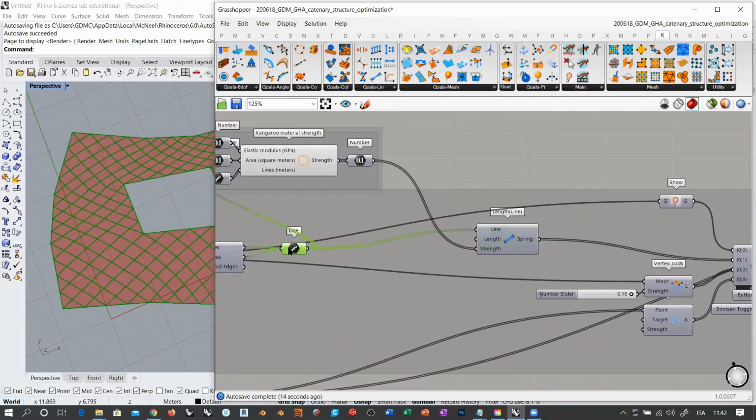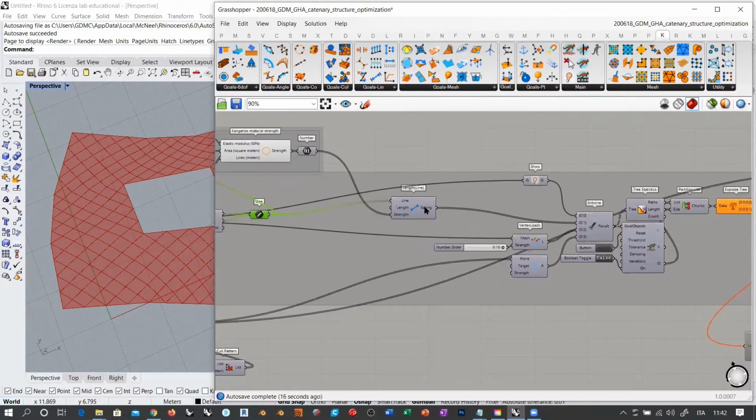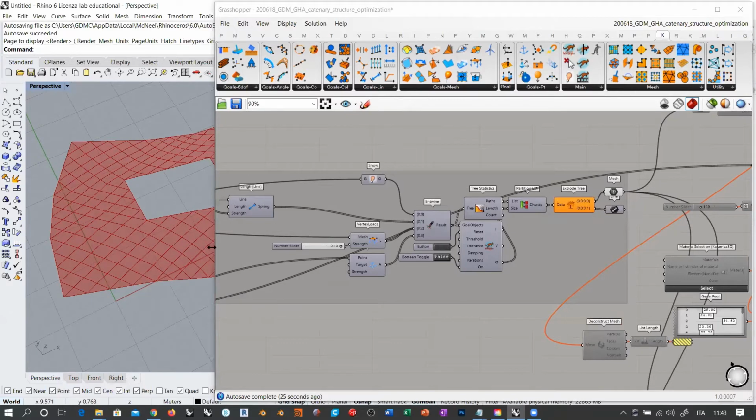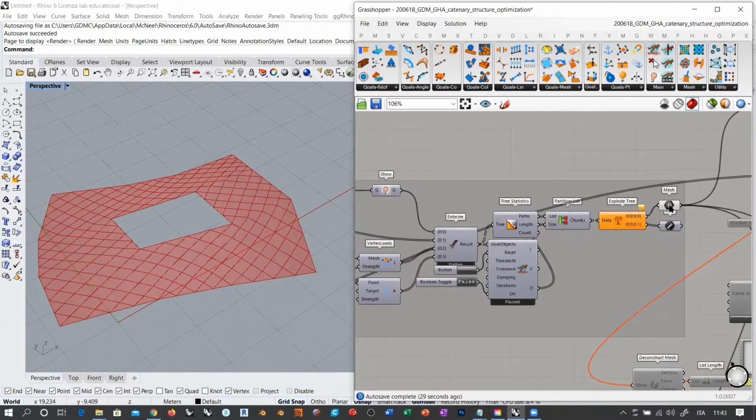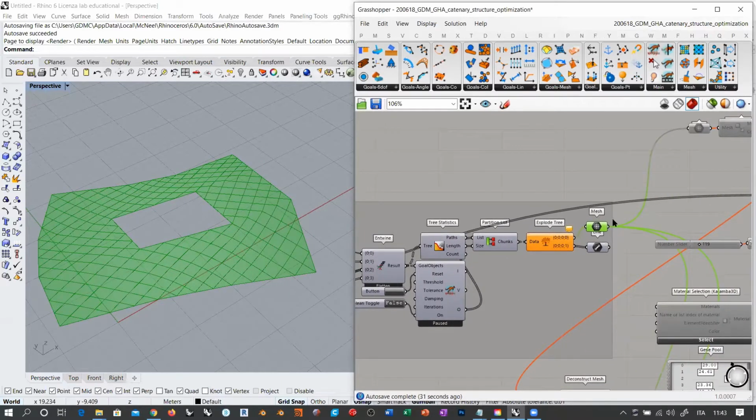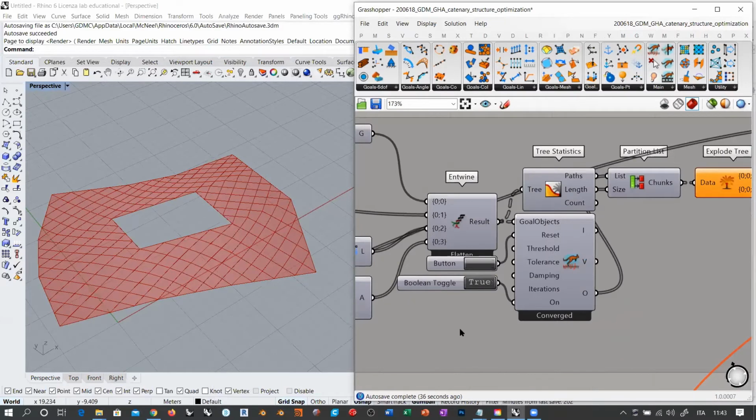Once you do this, you have an extremely stiff set of elements in this case, because they are reinforced steel. And the only problem that you have is not that it doesn't work, actually, but it becomes extremely slow. So take a look, for example, I'm going to concentrate on this mesh here. Take a look at this mesh. Now, this mesh is actually